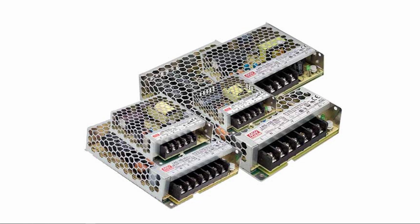Now, they don't all give you two terminals for each for minus and plus. Some give you three each for minus and plus. But these are what the power supplies look like. Looking at these, I see a screw hole or an opening in the flange there, so you could screw it down. I would not depend on that. There are brackets that you can buy that snap into the sides that fasten these down. And of course, the shell is expanded to allow air to flow through because they will produce heat.